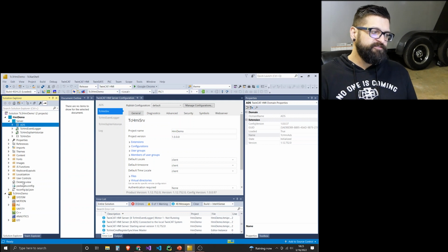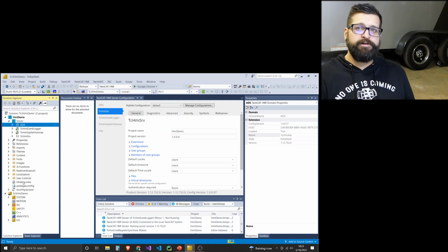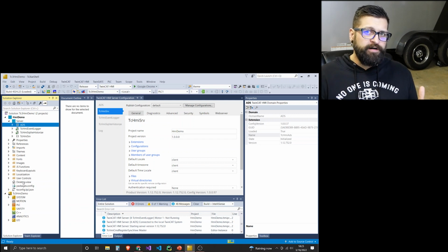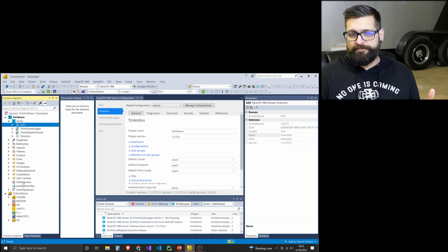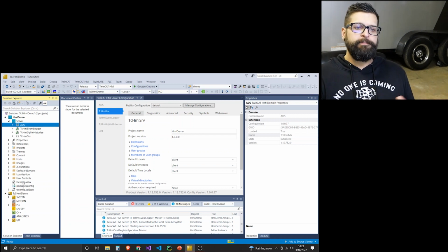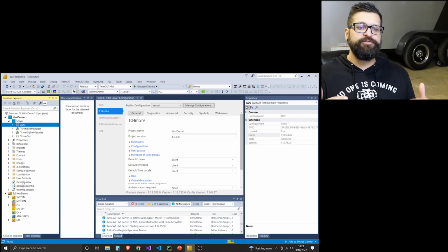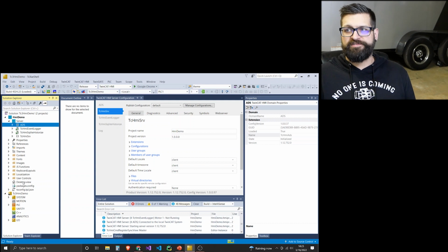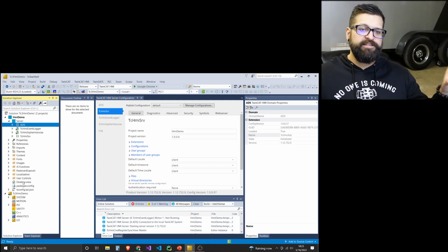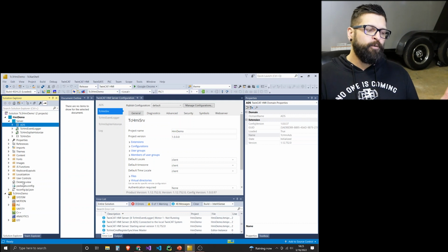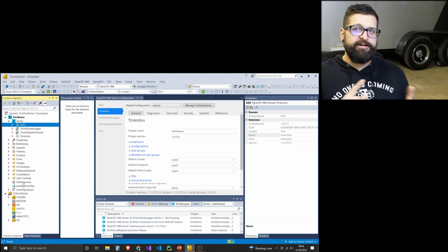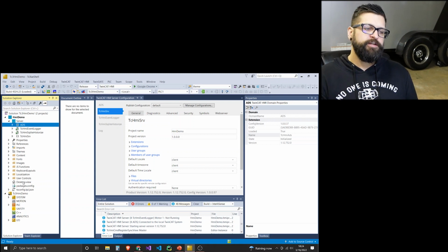That's really the workflow that we're going to use in the HMI projects: we're going to have some views. Deciding how many views you want will depend on how you plan on your operators using your HMI. Maybe you want 2 views because you're going to have 2 web browsers or 2 tabs open, both targeted to a different view, a different URL endpoint with the /, maybe one on home and one on alarm status, and you're going to display those on 2 different monitors. Or if you're going to have a touchscreen in kiosk mode where the operator can't navigate to other URLs, you might just have one view.